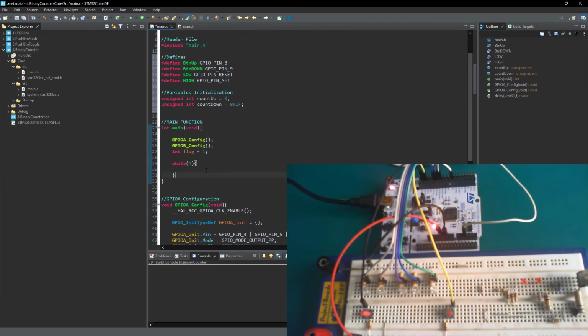So we can then come into our main function, the while loop here, our infinite loop. Now imagine the program has been loaded, nothing is being pressed. So what must the program do? We need to define that state, because it's a state. Pressing this one is one state, pressing this one is another state, pressing both is also a state. Now what if they are not being pressed? It's a state. So what are you going to do in that state?